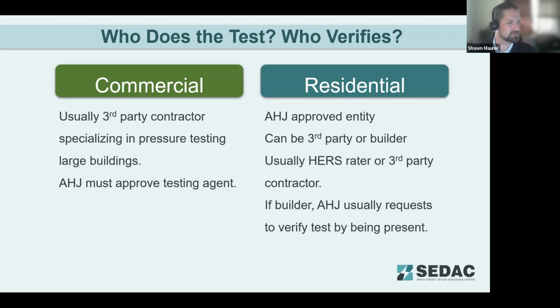Looks like we've got most of our poll responses in. Okay, so we did pick up, yes, 0.4 CFM per square foot is the air leakage limit. And the testing pressure, again, for commercial is 75. So yes, excellent. People did pick up on those.